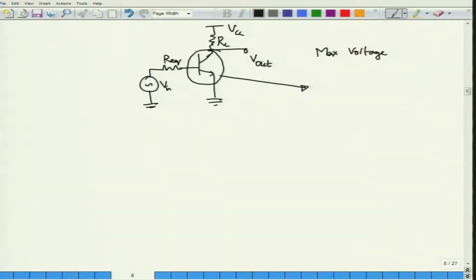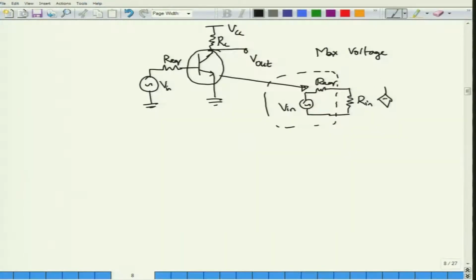So, if I think of this as a simple amplifier, then I know the input impedance of the amplifier to which I am now connecting the equivalent source and the voltage which I am amplifying. So, this is my input voltage. You can think of this as a practical voltage source that we are connecting, right. And then there will be some voltage gain, let us call that voltage gain AV times Vs, where Vs would be the voltage developed across R in, and then you will have some output impedance of the amplifier R0. To this you will connect the load RL, right,